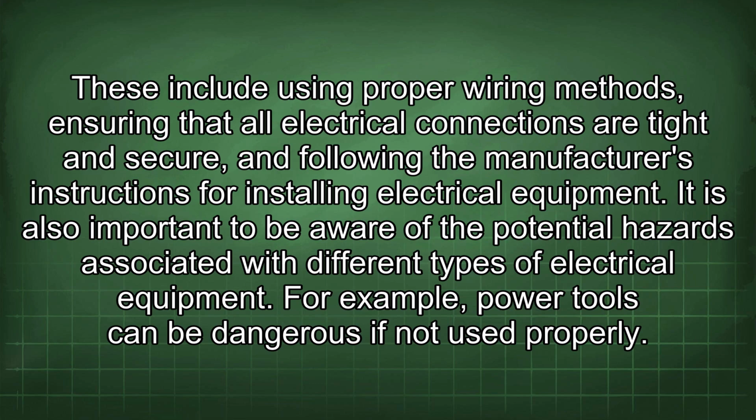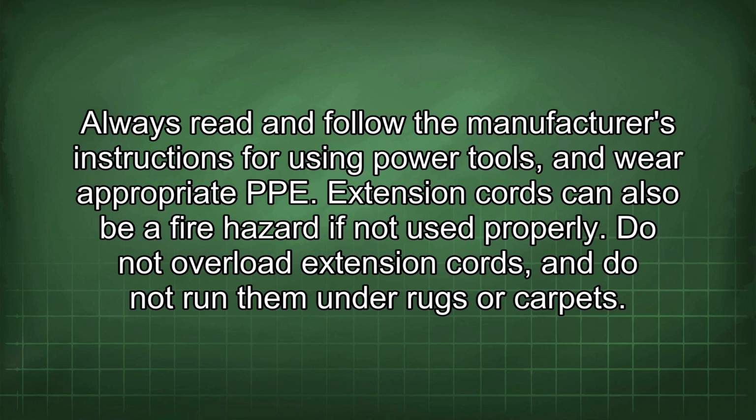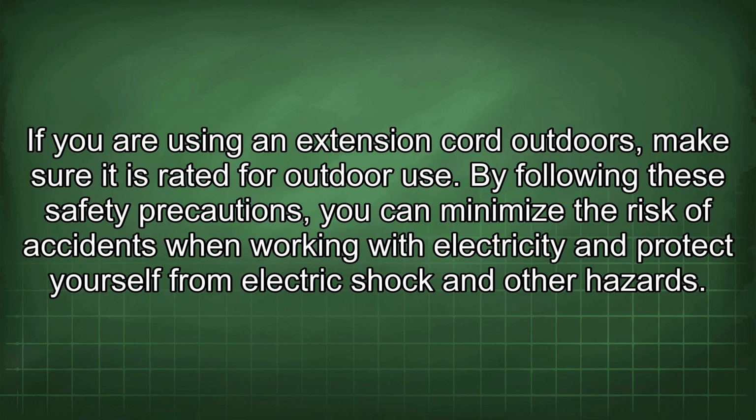It is also important to be aware of the potential hazards associated with different types of electrical equipment. For example, power tools can be dangerous if not used properly. Always read and follow the manufacturer's instructions for using power tools, and wear appropriate PPE. Extension cords can also be a fire hazard if not used properly. Do not overload extension cords and do not run them under rugs or carpets. If you are using an extension cord outdoors, make sure it is rated for outdoor use.